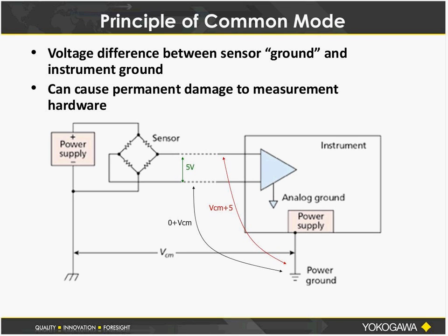Another type of common mode voltage condition that we see is if there is an offset or some kind of electrically active circuit, and you try to take a differential measurement of it. Things like taking a thermocouple measurement on a motor winding or anything exposed, or a transformer or some lighting hardware, can definitely introduce, or will almost certainly introduce, a common mode voltage.